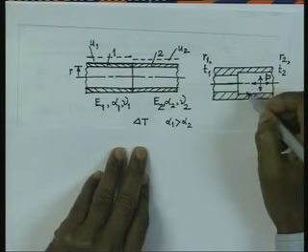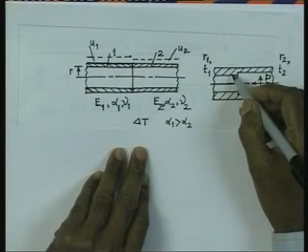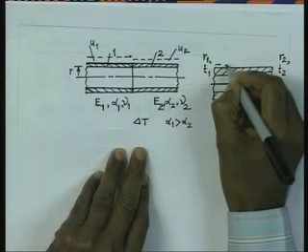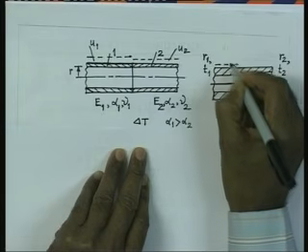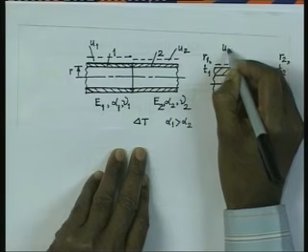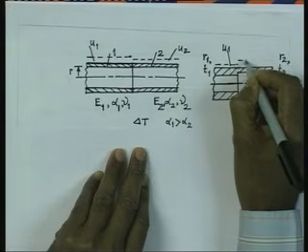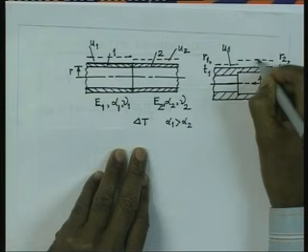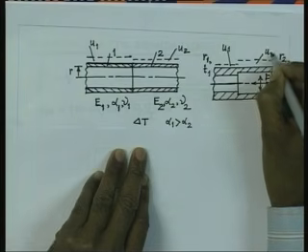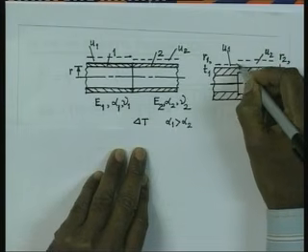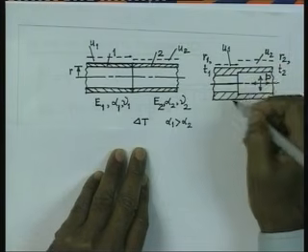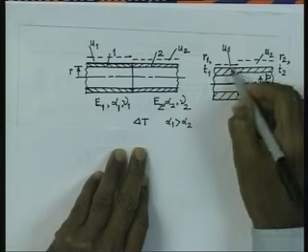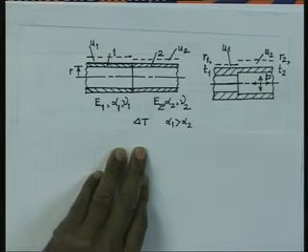Look at this case, herein the thickness is large, and therefore, you expect this pipe to expand radially by some amount, let us say again it is u1, and the one on the right is thinner, and it is subjected to the same pressure. So, it is going to expand more, and this is going to be u2. So, you find that because of the internal pressure there is going to be some mismatch in the radial expansion, and this will give rise to some stresses in this neighboring region.